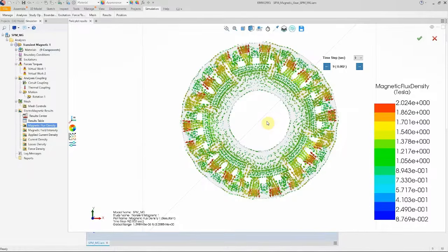You have to minimize the air gap, but it will have some mechanical issues for tolerances and production cost again. And the other one is we can use different pole pairs for gear ratio, but the torque ripple and of course again the production cost will affect our decision.